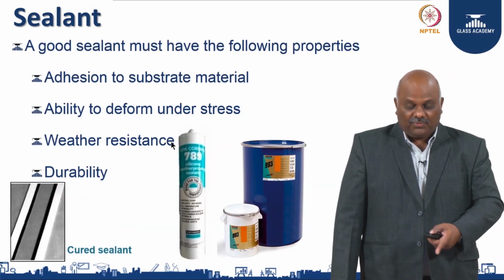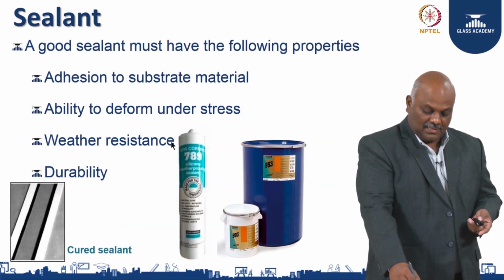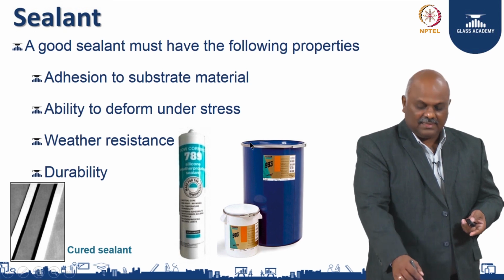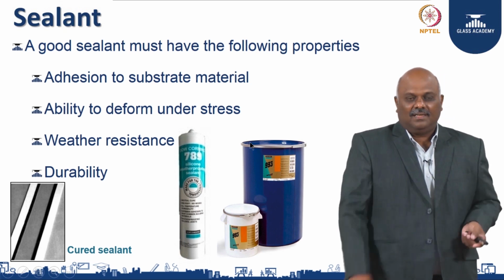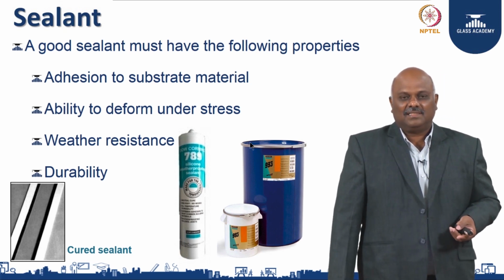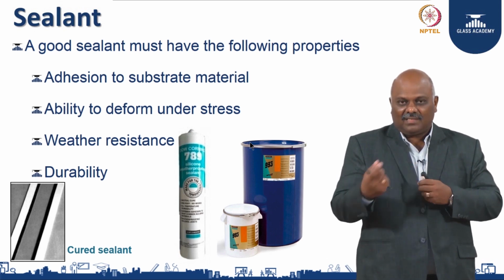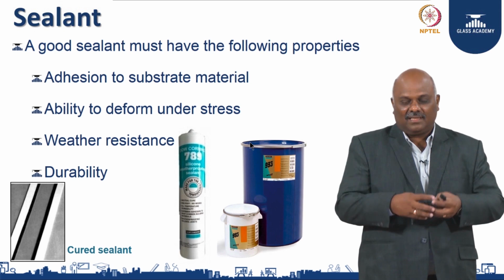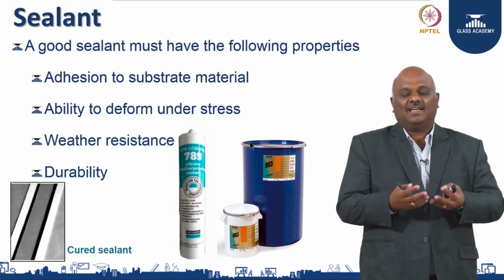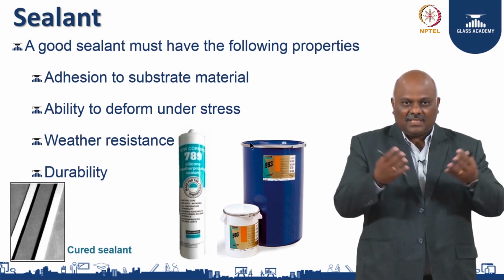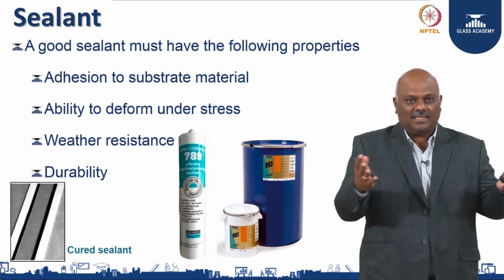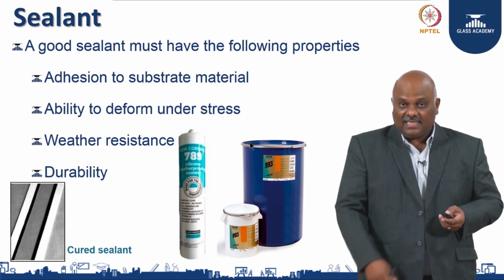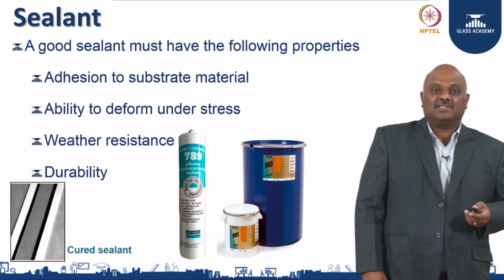They come in a tube form, or 2 part comes in a container like this. You mix them together like whatever adhesives you see, you have a hardener and you have a base, you mix both of them together, then they start chemically acting within a time frame, and then they get harder and harder as we go on.